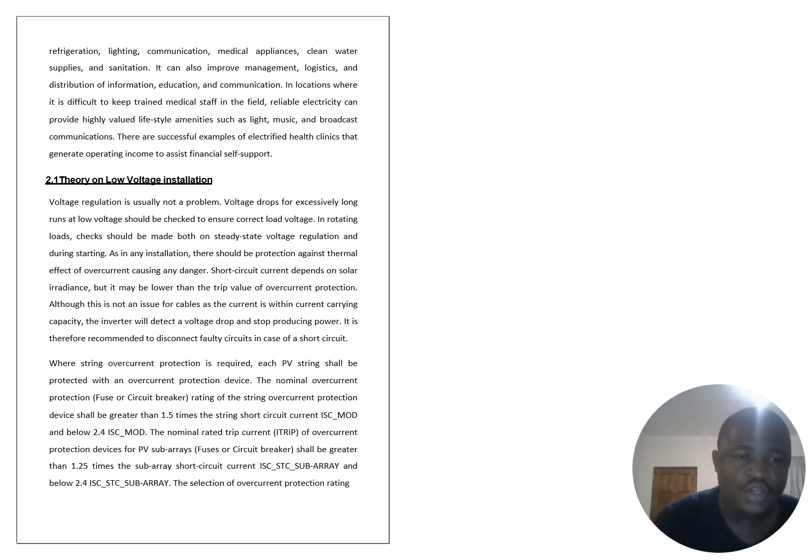Theory of low voltages. Voltage regulation is usually not a problem, but voltage drop for excessively long runs will be checked to ensure the correct load voltage. The rotating load should be checked in both steady state voltage regulation and during starting. As in any installation, there should be protection against the thermal effect of overcurrent caused by any danger. Short circuit current depends on solar irradiance, but it may also be lower than the grid trip value or trip value of an overcurrent protection.